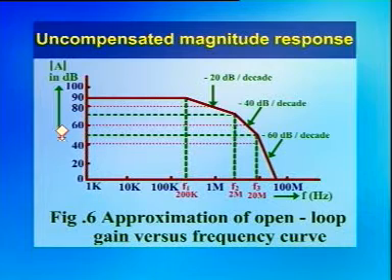If gain equal to 1000, that is AV equal to 60 dB, its projection falls on minus 40 dB per decade. Now the phase shift is 180 degrees and hence the amplifier is said to be unstable and should not be used without modifications. If AV equal to 40 dB, that is 100, its projection falls on minus 60 dB per decade section of the open loop frequency response, and the system becomes unstable and may become regenerative and may tend to oscillate.